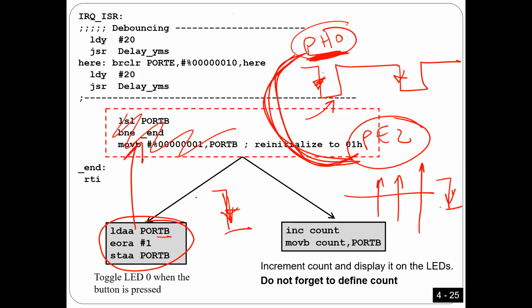That means every time this subroutine is called, someone entered the store. You understand what I'm saying? When someone enters the store, he or she cuts the infrared light, and that triggers an interrupt. So every time IRQ interrupts, someone has entered the store.